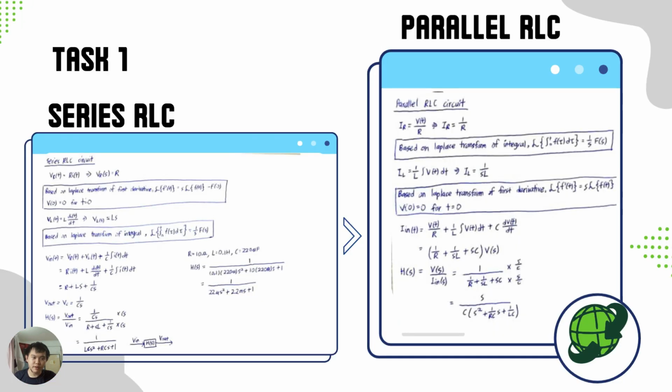So I'm going to talk about task 1, which is the Laplace transform of series RLC and parallel RLC. As we can see, for series RLC, the Laplace transform of VR is R, while we use the Laplace transform of the first derivative to get VL is LS, and the Laplace transform of the integral to get VC equals 1 over C integral of i(t) dt. So it's 1 over CS. Then we do some modification, and we get 1 over LCS squared plus RCS plus 1.